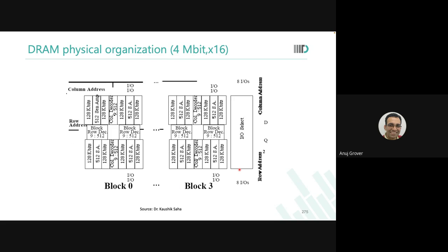ठीक है? Now, ECC design for a DRAM has to be done again very intelligently, where you have to take care of a lot of real physical parameters which could happen anytime, and also reasons why things could fail because of, as I just said, high energy particles striking your system. But it's an advantage of this system that the soft error rate will be limited, or whatever the soft error rate is, you can recover from it easily by the regular ECC that you have in your DRAMs.